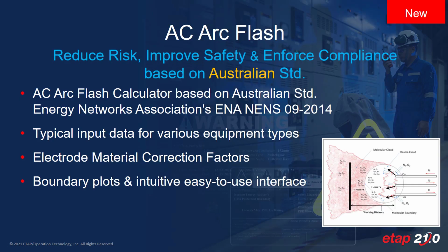Researchers from various countries have made significant contributions to the development of more accurate and conservative incident energy calculations. In Australia, the Sweeting method led the way by providing what many ArcFlash experts consider the predecessor model to IEEE 1584-2018. The Sweeting method, as published in the Australian Electrical Safety Standard, provided more conservative results than IEEE 1584-2002 for many years, until the 2018 standard was released.